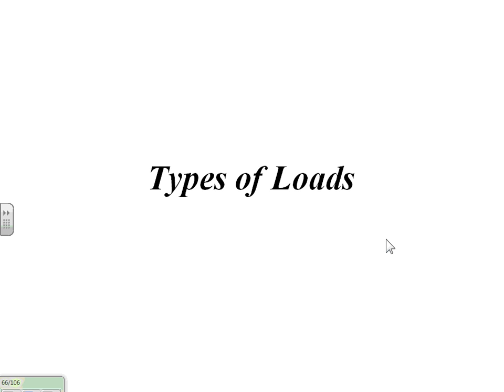Just one observation, Jerry, just for you guys, because Jerry talked about two types of transfer switches. The transfer switch that we're going to be using is not the closed transition; it's open transition in this project. It's auto open transition, the first type. The last type, the soft start that Jerry talked about, we're going to be using for the next project. Next project with Michelle Cooley, we're going to have a 4,000 amp switch here, where we're going to have a power circuit breaker, and we're going to do parallel with the grid. So the last type, the soft transition, just keep it in your mind for the next project.